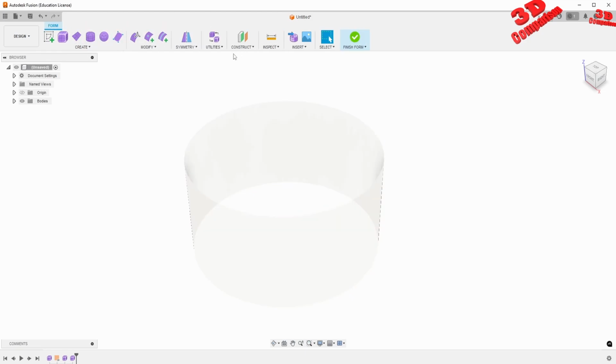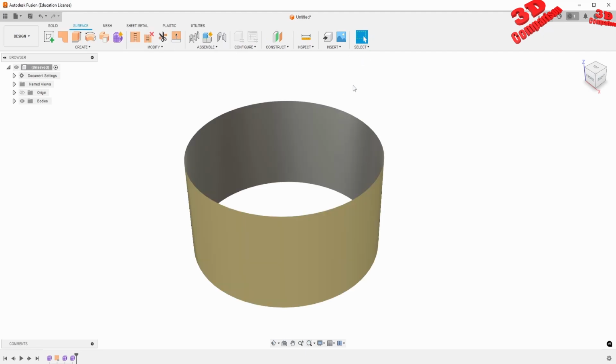You can generate something in freeform, similar to Imagine and Shape, and afterwards work within surface. But I have encountered many problems in some cases where I had to take the resulting surface, save it as a STEP file, and within CATIA I managed to do some additional changes to that. So that's one of the drawbacks with Fusion.